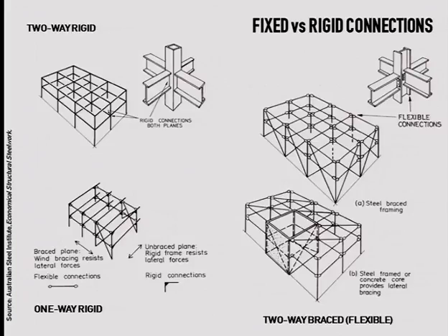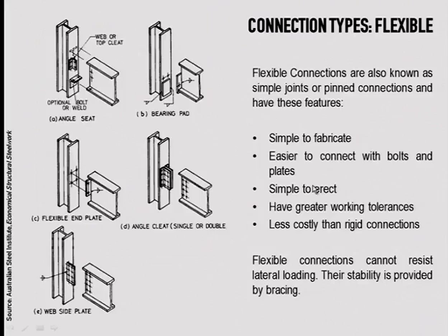It's not necessarily a disadvantage or an advantage. In most of the cases, we would like to have a structure that doesn't transfer bending moment to the external one. So it might depend on the cases. There is a huge difference between multi-story houses and skyscrapers in residential houses. So that depends on that. Just bear in mind you need braces in the case of these flexible connections.